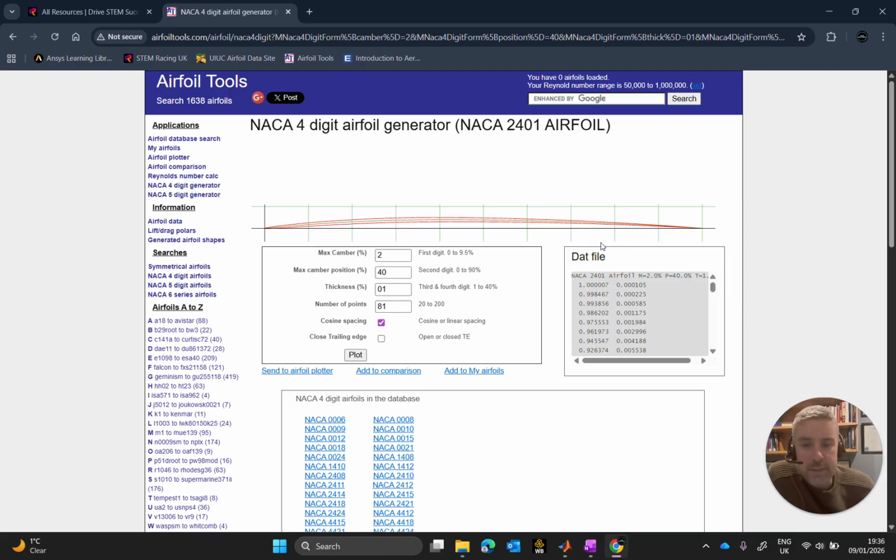And the other thing about it is something that we'll get into in the next couple of videos and towards the end of this. How do we test if what we're getting out of the computational fluid dynamics is accurate unless someone has empirically or experimentally tested a similar airfoil that has true values of how this performs? We can't just take the results that we get out of our own computational fluid dynamic analysis and assume that they are right. In fact, we should assume that they are not right, that they're incorrect.